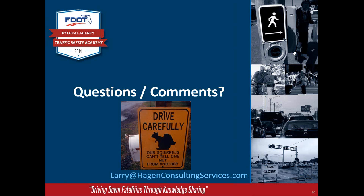If they're in the inside right turn lane, the guy on the outside right turn lane has no chance of being able to see at all. And so it can get kind of iffy, but it seems to work okay there. I hadn't seen any crashes or any reports of crashes like that with those right turns on red. But I would typically, especially if I was into triple rights, put the sign up to say just the outside lane can make the right turn on red.